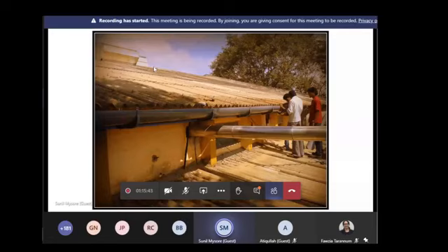This detail I am not going to tell you how to fix or how to draw, because it will take a lot of time. But you have to give some cognizance to the detailing, like how to fix the gutter. It will generally come from practice. Otherwise, you have to push the gutter a little inside, so that even when the water sticks to the walls of the asbestos sheet or the wall, the water ends up falling inside the gutter and does not leave outside.